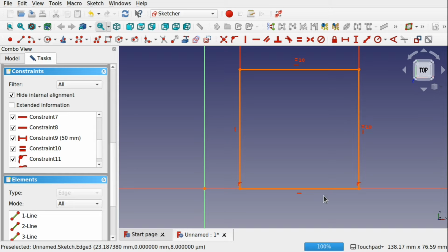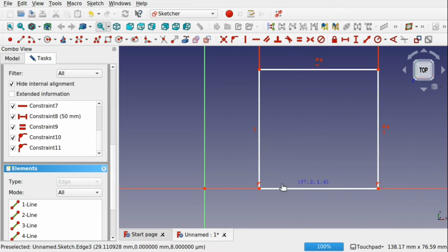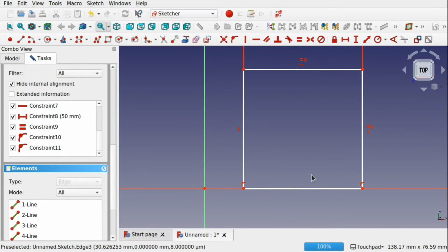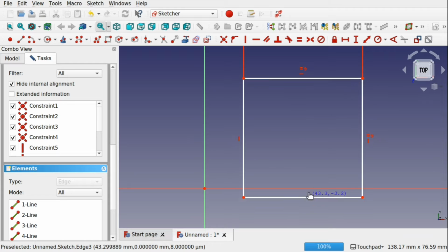The same with CAD. In that you have constraints here that have constrained it to that line, but you've also got a horizontal constraint. That line is horizontal, so there's no point in having either this constraint here or this horizontal constraint. So we delete that, and now that is free to move, and its constraints, that horizontal is constrained. So we're trying to fully constrain this, so I'm going to take this off this line because there's no point in having it on this line to fully constrain it, because we can't constrain it fully to that line.